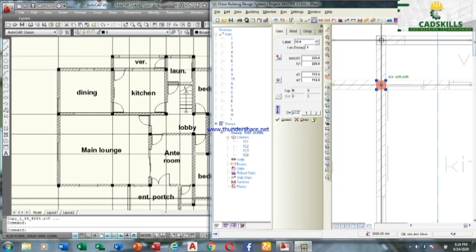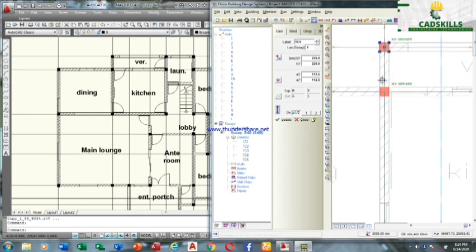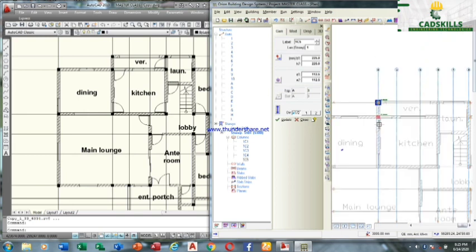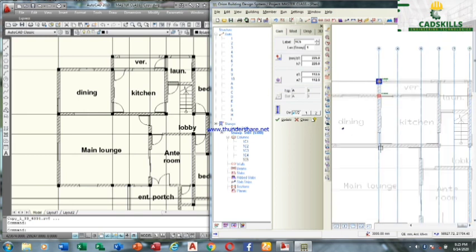put here. Now note, columns do not enter where there is no cross line. Columns enter only where you have cross lines. The center, that is where it enters. It can enter here, though this is a grid line, except I cross a line here for the column to enter, because that is what we selected. Alright, so I continue.